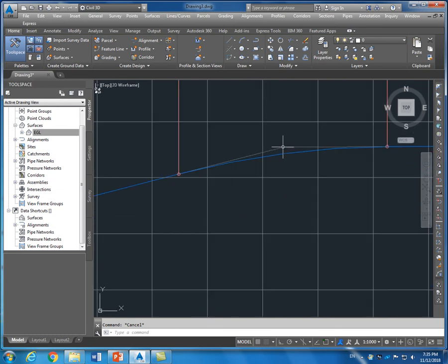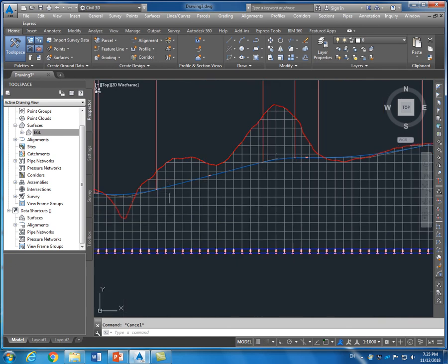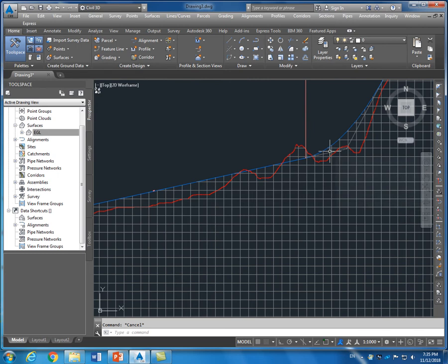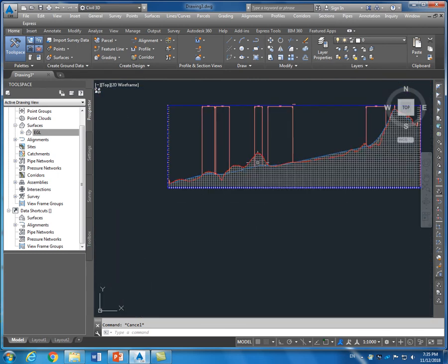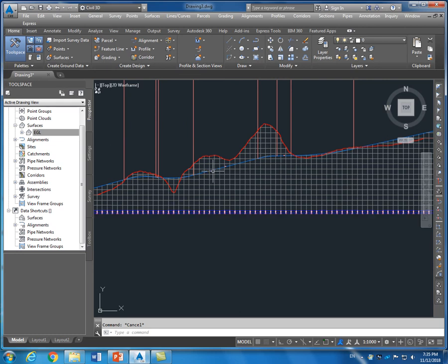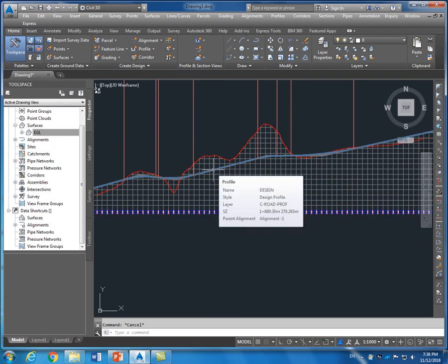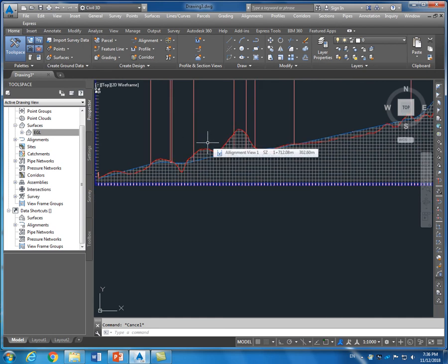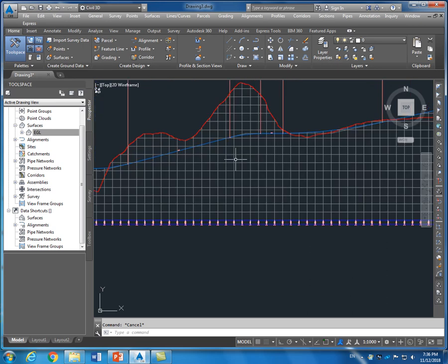Here is your PVI, but in that process actually you'll have more cuts here. But the good thing about design is that there is nothing called wrong in design. So maybe you can do trial and error, and in several iterative steps you can find out the best path that reduces the maximum cut and fill. So for the sake of this demonstration, I find this is okay.